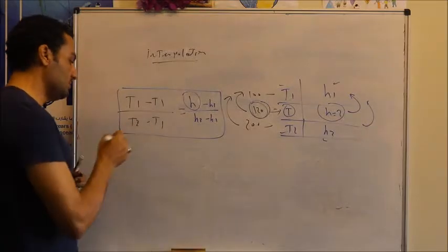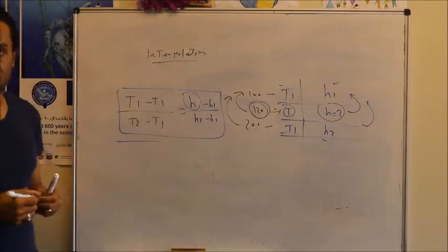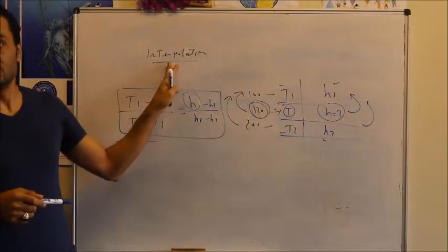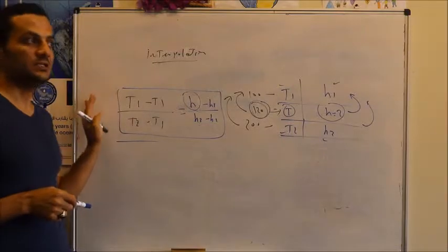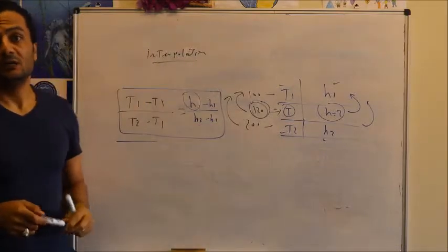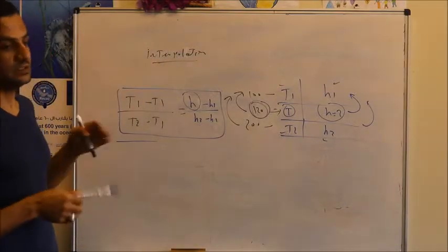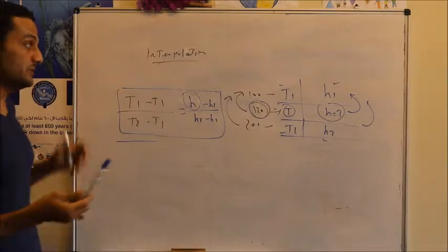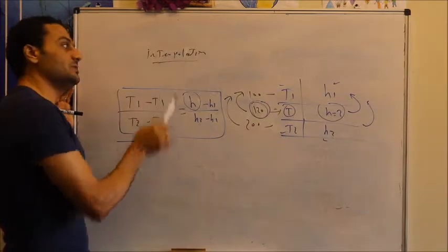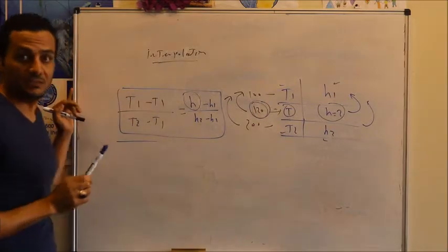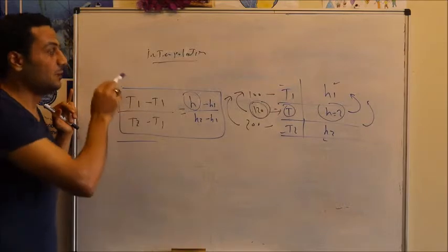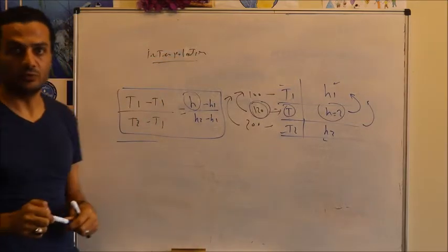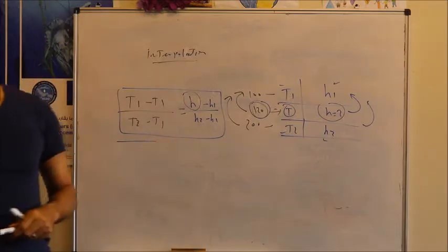For the refrigerant tables, the same procedures are applied, but instead of tables A4 and A5, it will be A11 and A12, and instead of table A6, it will be table A13. Now, if we have a refrigerant in the subcooled zone, I have made the check and I find the status is subcooled. So in this case, we don't have a table, and we can apply the same assumptions that we made for steam. We can assume all properties are equal to the saturated liquid properties, and we can continue the solution.